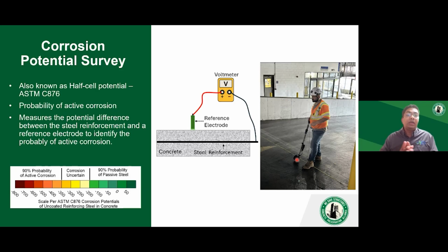But it all depends what the temperature is, if you're electrically continuous or not, if there is any waterproofing coating, because this technique does not really work if you have any traffic membrane or asphalt overlays on it. It has to be bare concrete surface. In such cases, we do the survey from the underside, and doing the survey from the underside can be time consuming.